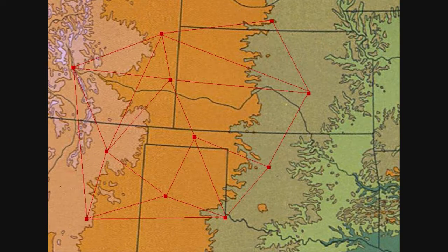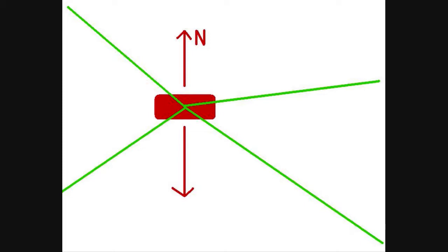Moving on now, we're going to zoom even further down to the individual station itself. The red lines you see are the North and the South Pole lines. These are the stations positioned to the North and South Pole. Magnetic North and South Pole. We don't use geographical North and South Pole. The green lines you see, however, are the actual vectors, the lines that you actually fly across, past the station, over, and onto your destination.